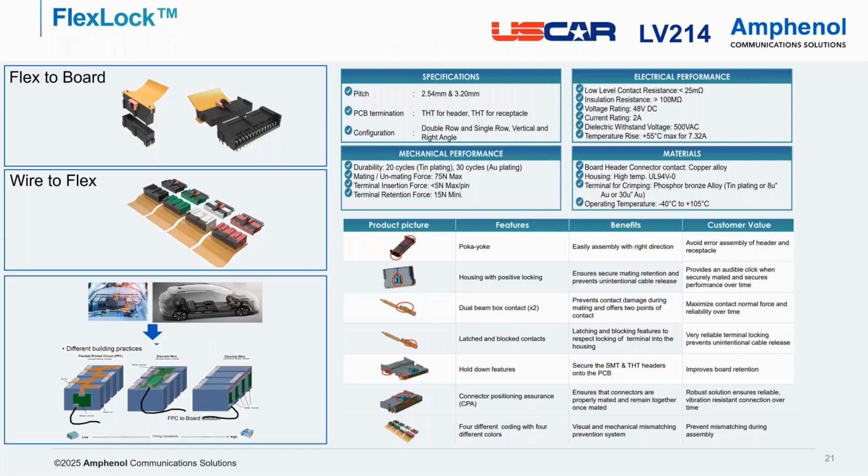Here, this is a more traditional way of connection. What does that mean? That means that you have a terminal and a male pin. So you have a metal terminal system on the side of the flex, and on the other side, what you solder to the PCB, you have a male pin. This female terminal is then soldered to a flex.